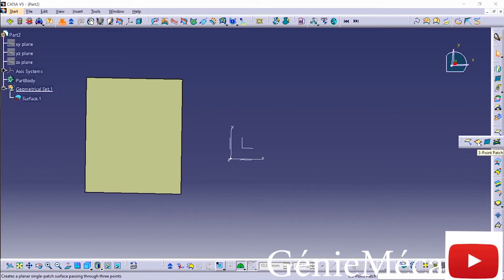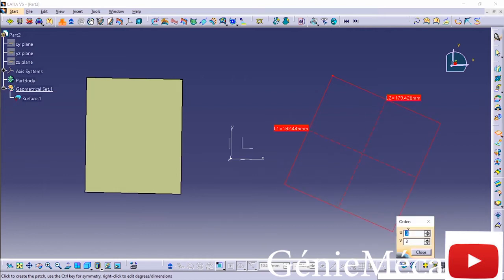If I want to space, or in this case, corners or vertices off of adjacent surfaces that you want to use. And this allows you to pick 4 points, and no, they do not have to be planar. And then once I pick that 4th point, the surface gets generated. Again, none of these are history-based. As you can see, they're all NURBS-based surfaces.